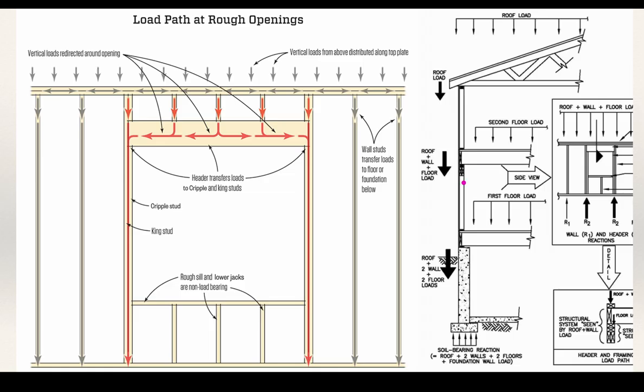Now, if we were to look at the position of the lintel in the wall, so this lintel, the purple one down here versus the orange one up here. Obviously, the purple one is carrying more weight because it's carrying the weight of this floor, and anybody dancing or having fun up here, playing piano, whatever heavy things you have on that floor, plus the weight of the roof.